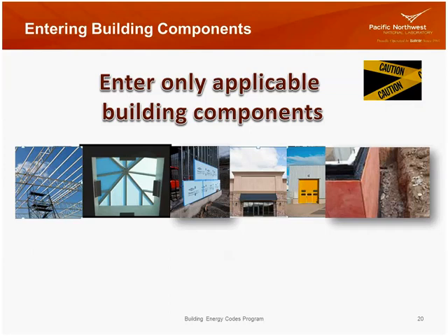So let's take a look a little quickly here at just building components. For the envelope, if you were just doing envelope compliance, what does that involve as far as what you would have to put into COMcheck? Really what you're doing is you're taking those building plans and you are defining the building thermal envelope. So you're not putting in and defining any interior walls between conditioned spaces, any interior floors. It's only the exterior thermal building envelope that defines that conditioned space or semi-heated space, depending on where your project is, that's either separating conditioned from unconditioned or outside air.